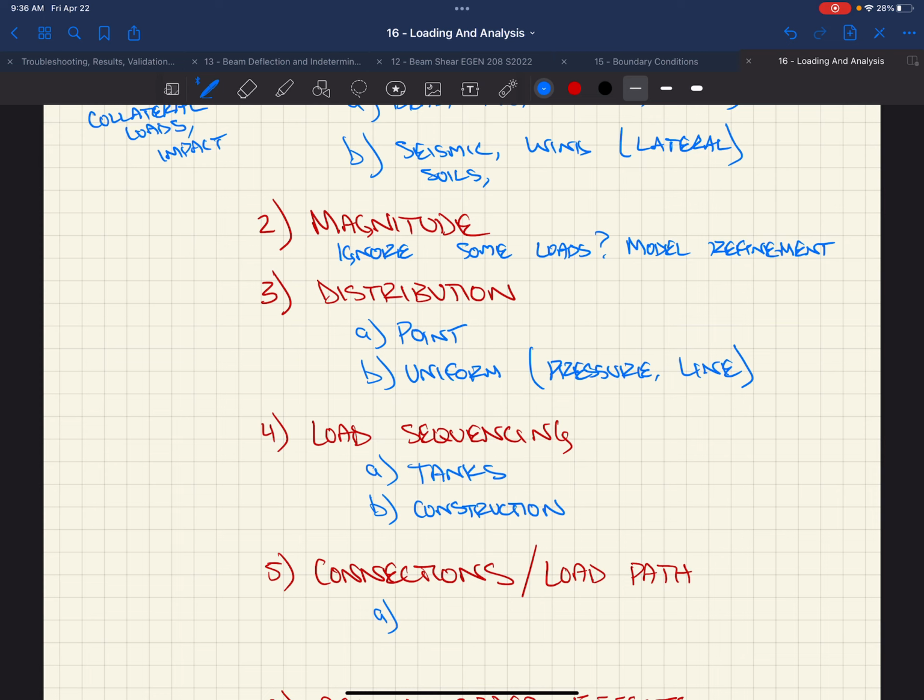So yeah, you have no soil pressure, you have all the water in it, and that honestly is usually what designs the size of the tank. Because you get this 62.4 pounds per square foot per foot height of these walls, right? And a lot of times soil pressure is somewhere around 40 to 60. So at that point you assume that it can be full or it can be empty, right? So sequencing can be big.